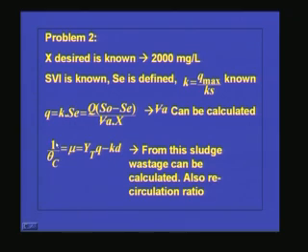And we have another equation: 1 by theta C, that is the minimum biological sludge retention time we have to provide, which is equal to mu, which is equal to Y times Q minus Kd. These expressions we have seen already, how we are getting them. So, if you know this, and we know what theta C is,